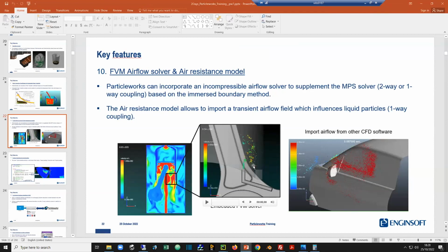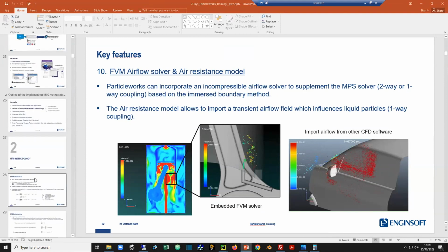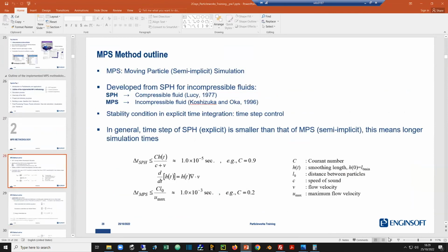One is more focused maybe on the air simulation, the other more on fluid, splashing and jets. Lattice Boltzmann, for instance, is widely used, I think, in external aerodynamics. Actually, Particleworks has a lattice Boltzmann solver inside for the air simulation. We got a clarification from Jousef that it's not meshless but works with lattices, which is a concept introduced yesterday. But this particle method is quote unquote meshless, whereas LBM is lattices. Got it.